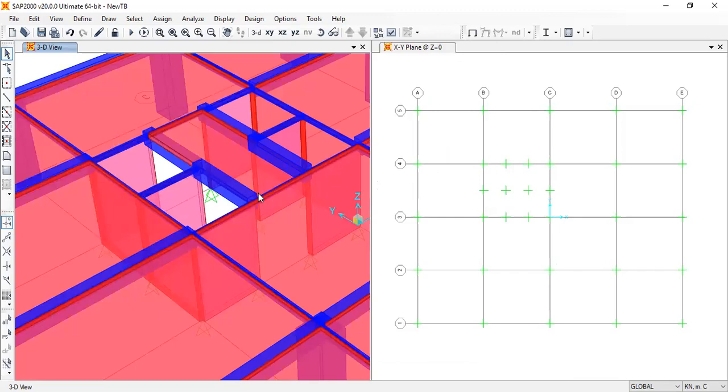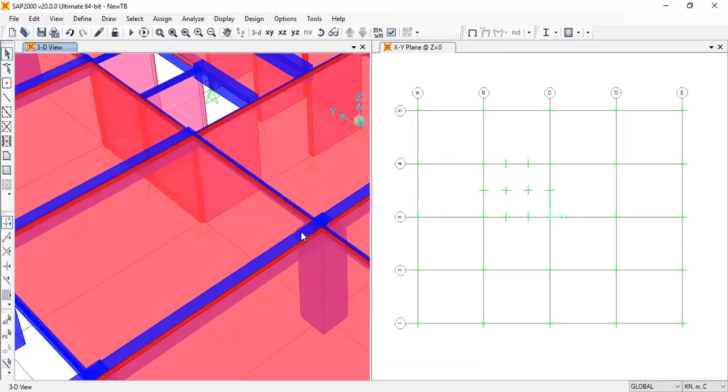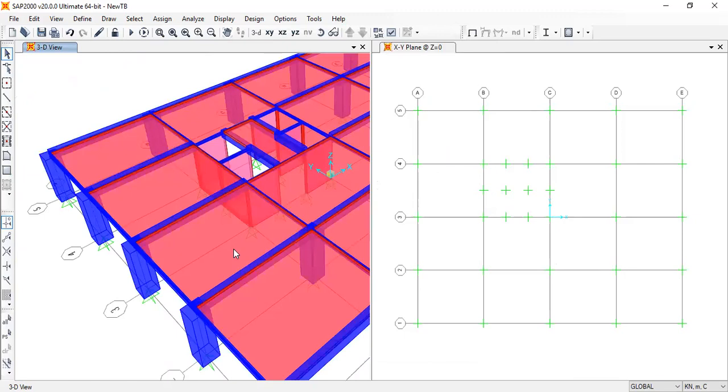This is a small beam which is connecting this for the load transfer. So I will not load the slab because you know these quadrilateral elements, right? A four noded element is connected only at these four locations. So that's the finite element, right? If you need to increase the load transfer, you need to mesh it so that these points also will be connected to the slab, and the more you mesh it, the more accurate the results will be, right?